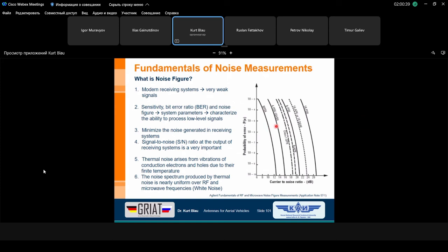Again, these two signals have no modulation or no change of the magnitude. Only the phases switch. It means we have the same magnitude. Then this goes up to the state here of 8 different phase states, which means all the signals have the same magnitude. Only the phases switch between smaller amounts.